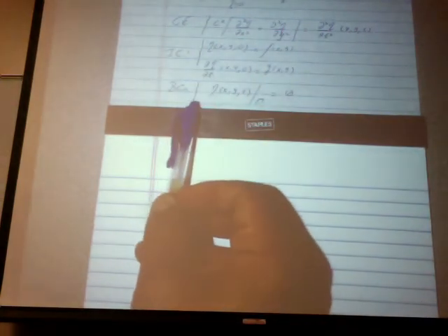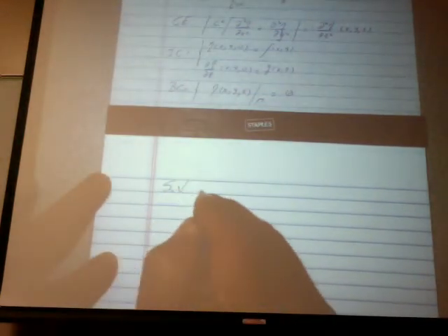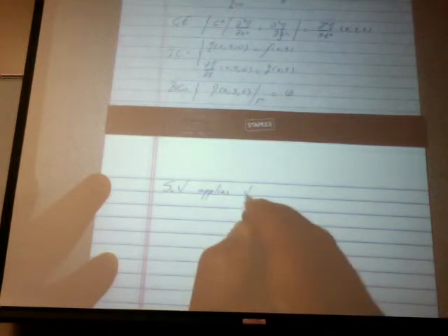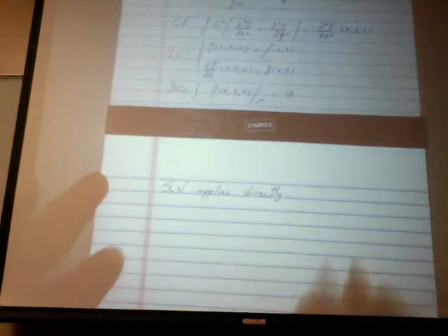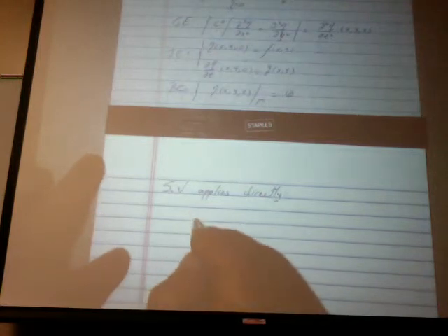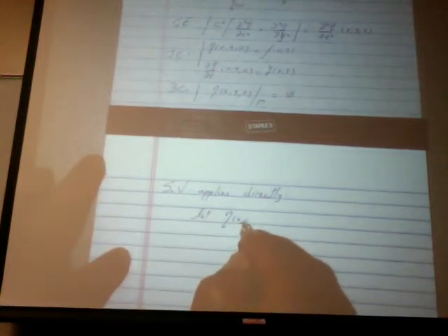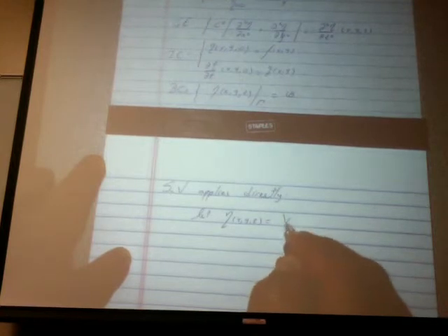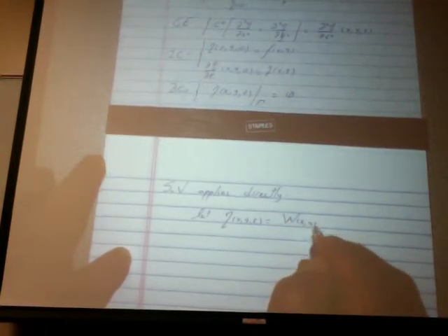So because we have a homogeneous governing equation, homogeneous boundary conditions, and non-homogeneous initial conditions, it doesn't matter that there are two non-homogeneous initial conditions, separation of variables applies directly. So we're going to let eta of x, y, and t be equal to some function w of x and y times some function tau of t, separated into space and time like we do with multidimensional transient problems.